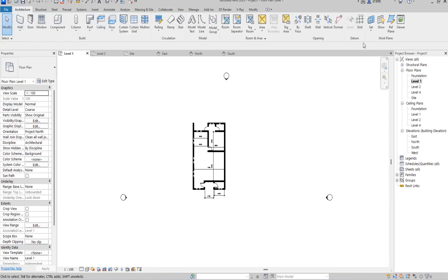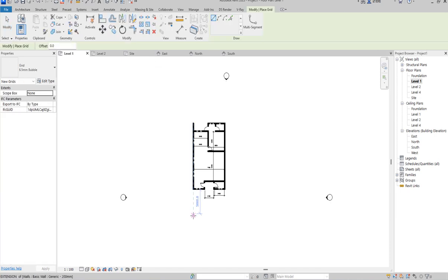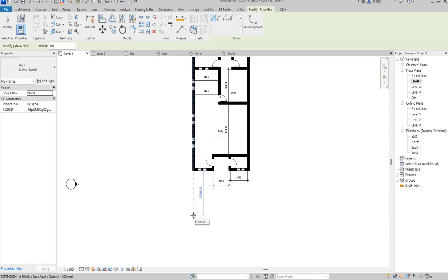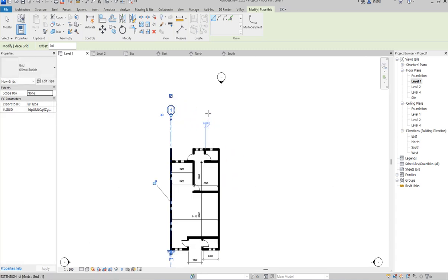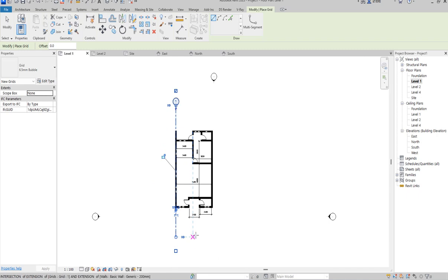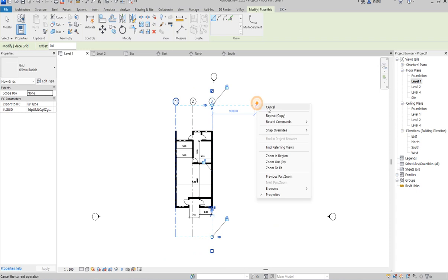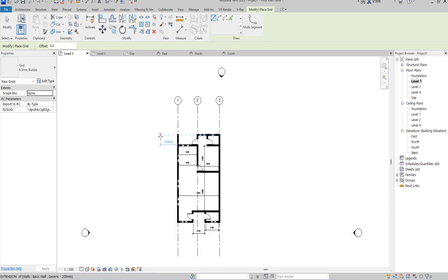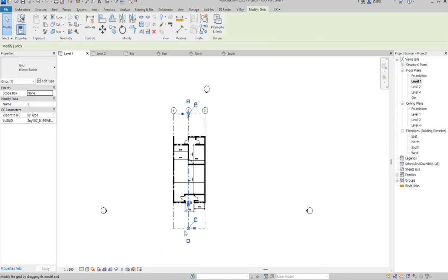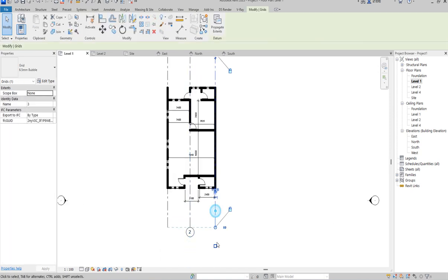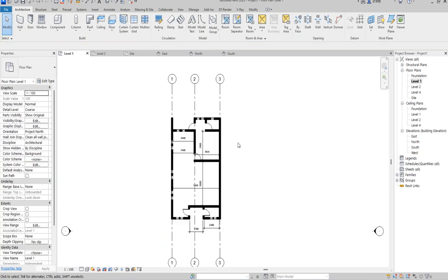The vertical grid first. That's what we're going to create only on this one. So when you are selecting grid, let this be at the center of your wall. I'm going to indicate that is the beauty of Revit. It snaps to the center. So you work on this one as well, and you do this one. So you have 3 grids in space like this. You can do the horizontal maybe later, but not now. So as you have this one, you can just double-click, so that you go to the first side, and they will be labeled. So that is what we want to do here.